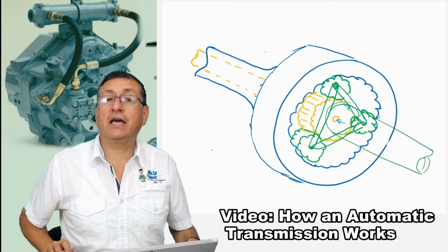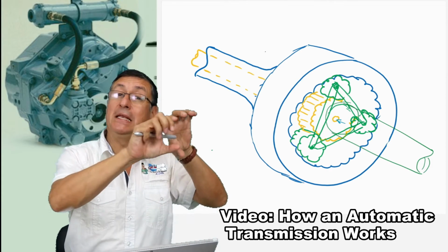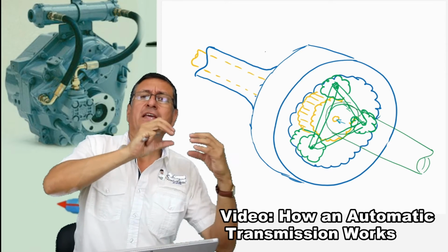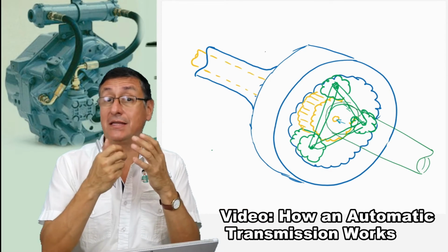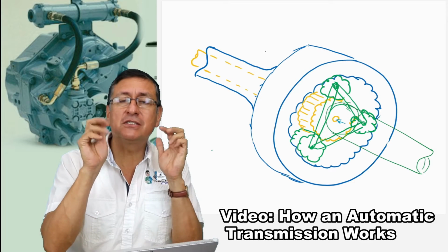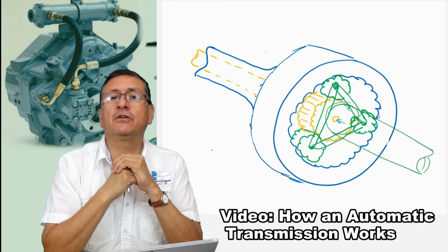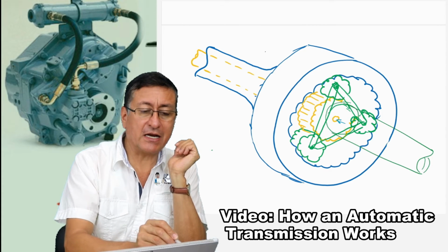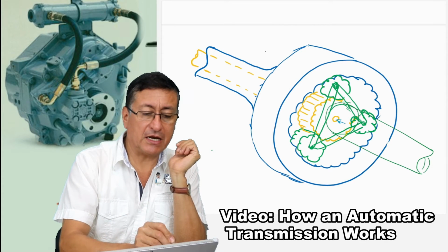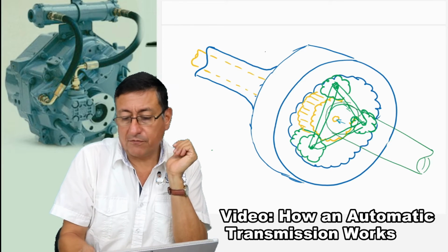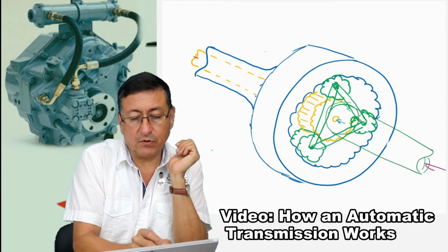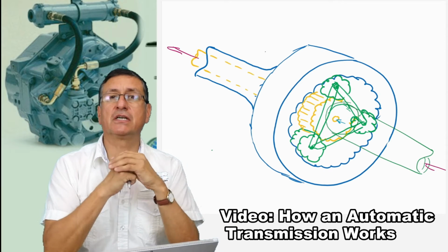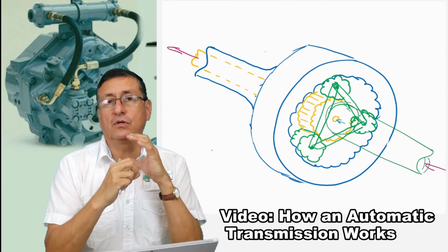In this particular case, we have 3 shafts completely aligned, or you can put all of those 3 shafts one inside of the other one. This is the magic secret of the automatic transmission. And of course the fluid is passing internally. The fluid enters over there, and the fluid passes completely through the pipes, through the shafts of the planets or the sun or the rings.